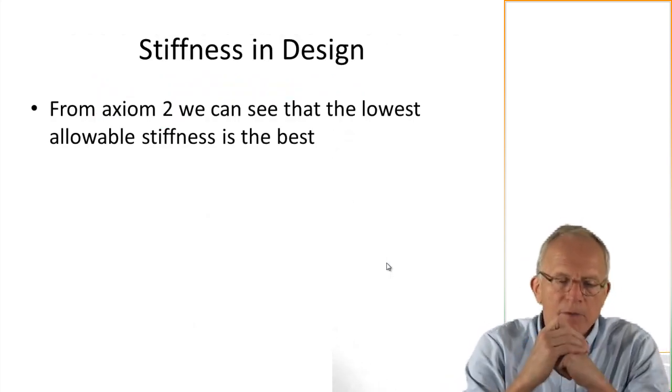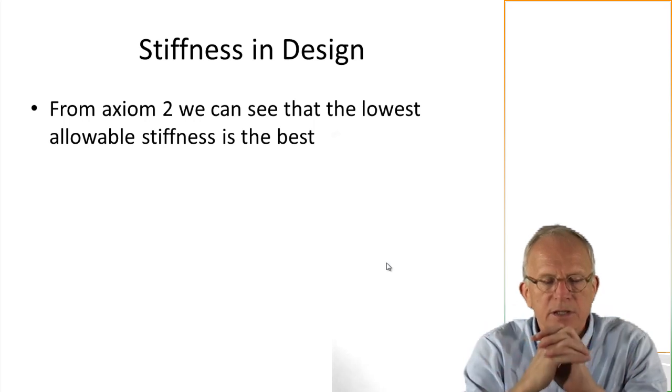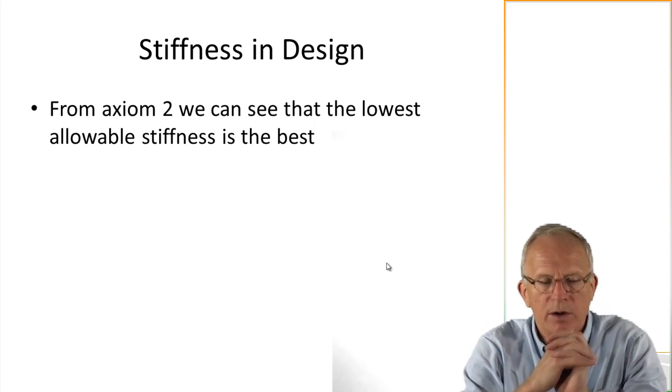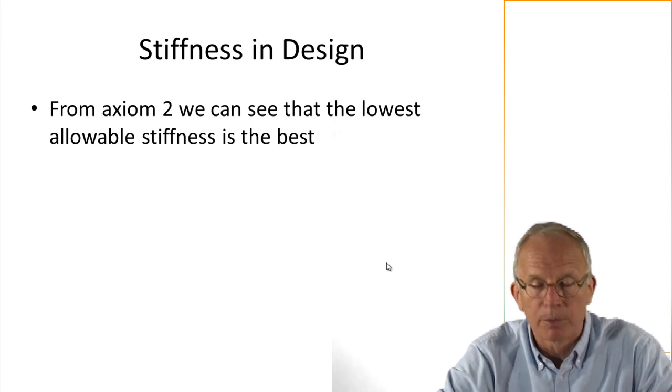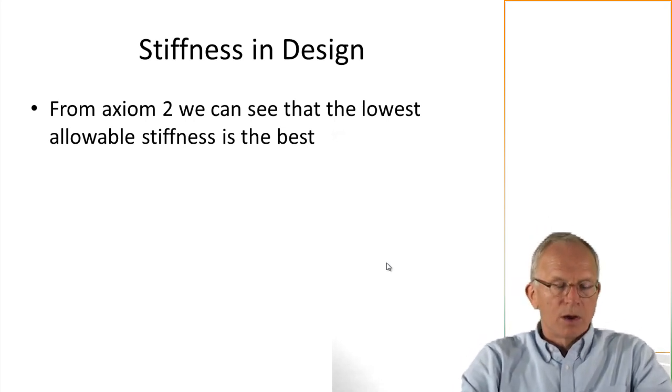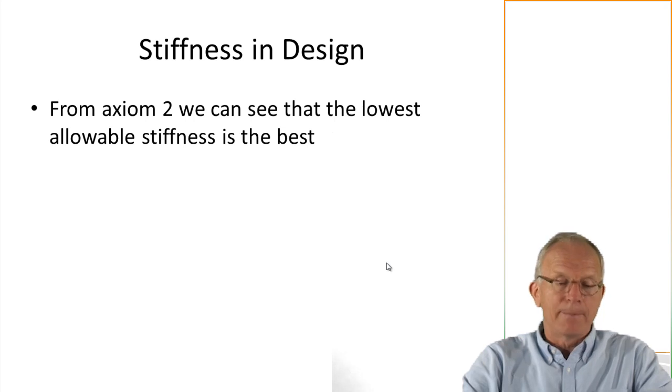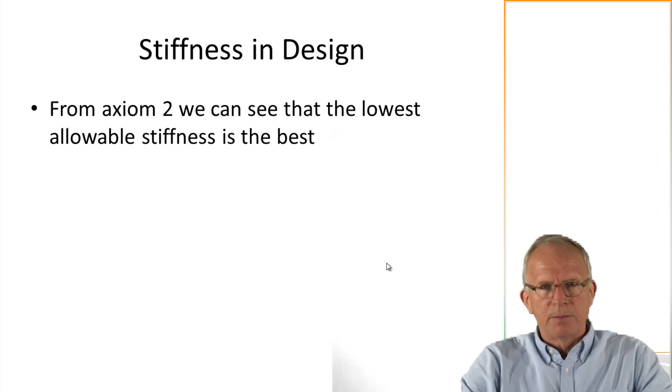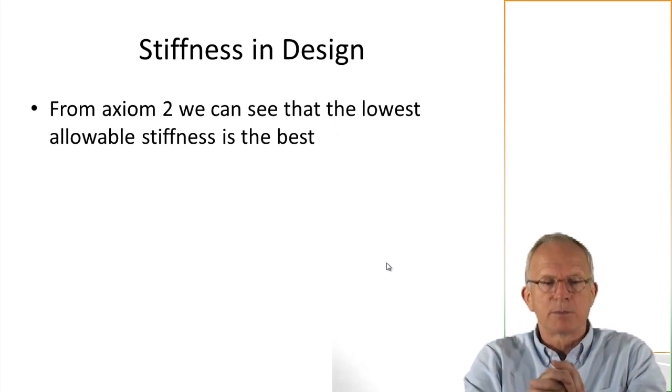So this can be a metaphor for different kinds of stiffness, and what we want to look for here is the lowest allowable stiffness. So why wouldn't you go with an enormous spring that was very soft, and then you would have a huge tolerance? In this case, you'd need a huge cam, and so we would certainly exceed some sort of constraint if this were to be, say, a feature on a chair. So we would want the whole system to be inside some reasonably sized package.